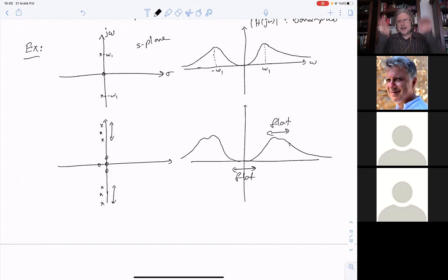That is the passing frequencies from here to here, let's say. And it is stopping here. So these are the stop, these are the pass. If I want to pass, I put a pole near to those frequencies. If I want to pass around the frequency range, I'm just putting poles over there. But the total number of poles and zeros is also critical here.